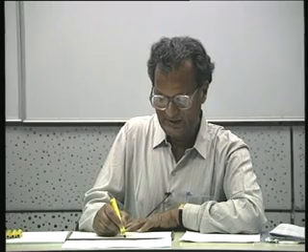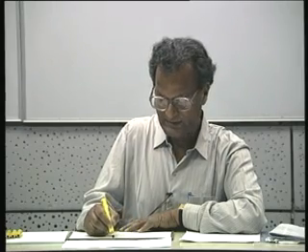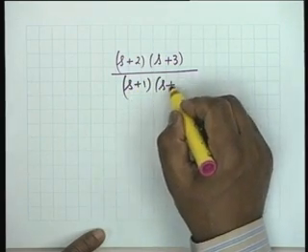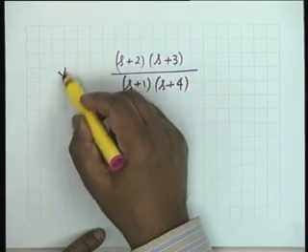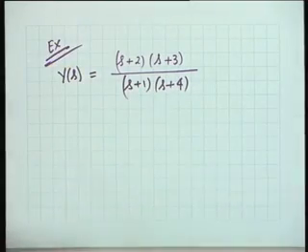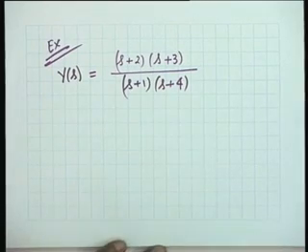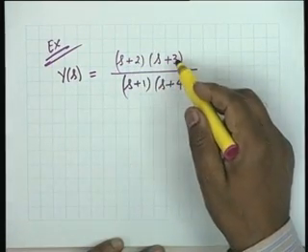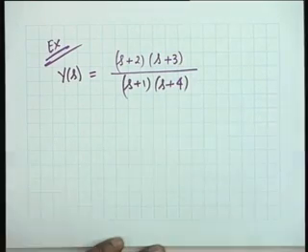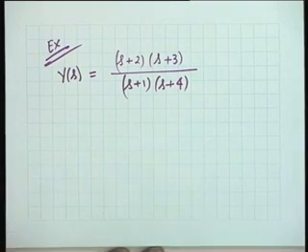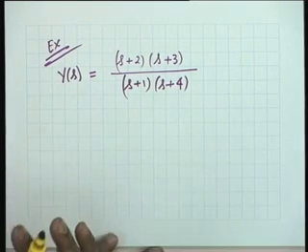All right. Now this problem is slightly tricky. s plus 2, s plus 3 over s plus 1, s plus 4. Suppose this is given as an admittance, y of s. Now the poles and zeros do not alternate. The first critical frequency is a pole, but then you have a zero, another zero, adjacent zero, then a pole. First is a pole, last is also a pole. So it cannot be RC or RL. It is not LC at all.